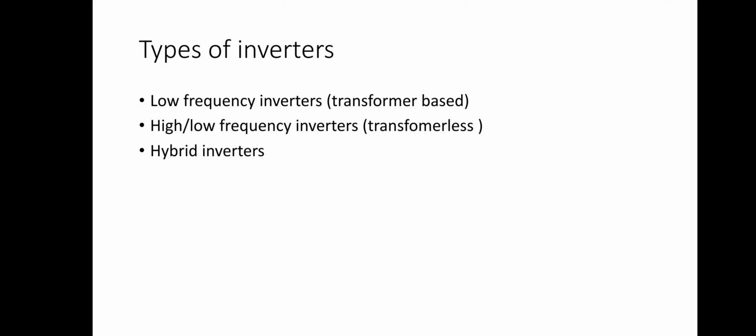Now the high low frequency inverters, why I use the high low as a term to describe this inverter is it has two chambers inside. It has a DC to DC converter. When we go there, I will explain further. It has a high frequency chamber and it has a low frequency chamber inside of that transformerless inverter. Those ones do not use transformers, they use a couple of inductors, boost and buck converters to generate their own kind of energy. Then the hybrid inverter is not different from the two inverters I've listed above.